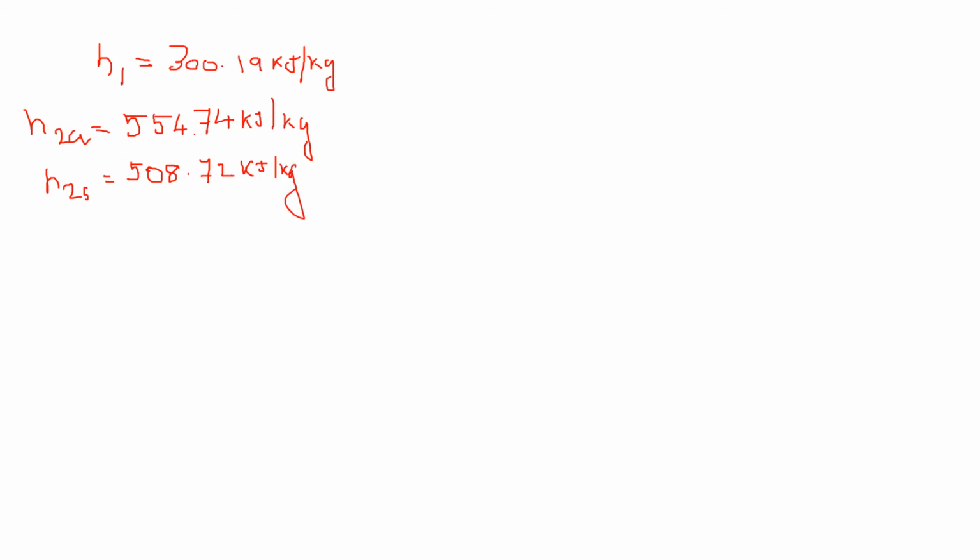Okay, now we know, because for a compressor, what is the minimum one? We know it is the isentropic one over the actual, right? Because isentropic one will be the least work given. Because what is a compressor? A compressor is the work consuming device. A turbine is a work producing device. So always the isentropic one will be the least one for the power you need to give, and the more one will be giving output, because that's how you make the difference between compressor and turbine.